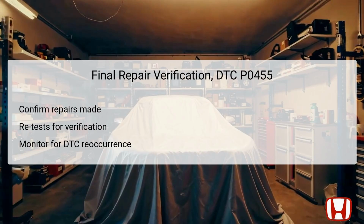After rerunning the EVAP function test, technicians should monitor for any signs of the DTC reoccurring over a few driving cycles. Ensuring that the issue has been fully addressed means not only fixing the symptoms, but also confirming that the root cause of the problem has been resolved. An effective verification process is vital in maintaining vehicle performance and emissions compliance.